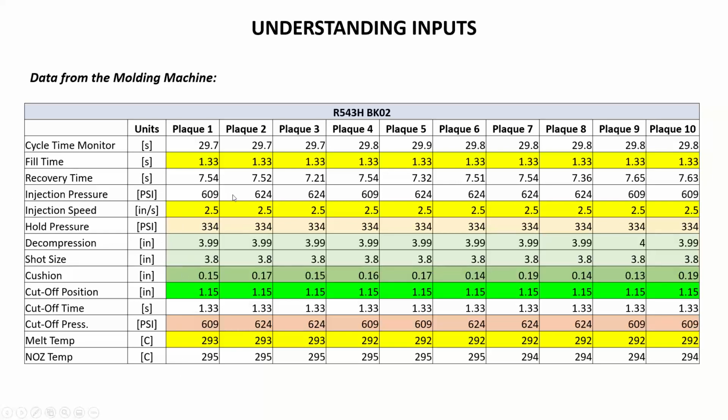The injection pressure listed here is the pressure when you hit transfer. The hold pressure is the pressure that's applied when you're at the point of cushion. In the case of the transfer pressure, that's not a uniform pressure throughout the cavity to the end of the fill, because it's going to scale from that pressure to zero or near zero at the flow front.